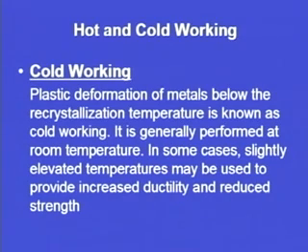In some cases, slightly elevated temperatures may be used to provide increased ductility and reduced strength. As we have seen, whenever we heat the metal, it becomes ductile as well as the strength also reduces. So, if under certain circumstances we need to work on a metal whose ductility is not up to the desired levels, we may slightly increase the temperature of the metal, but it will never go beyond the recrystallization temperature. So, slight increase in temperature is possible, but it will not exceed the recrystallization limit.